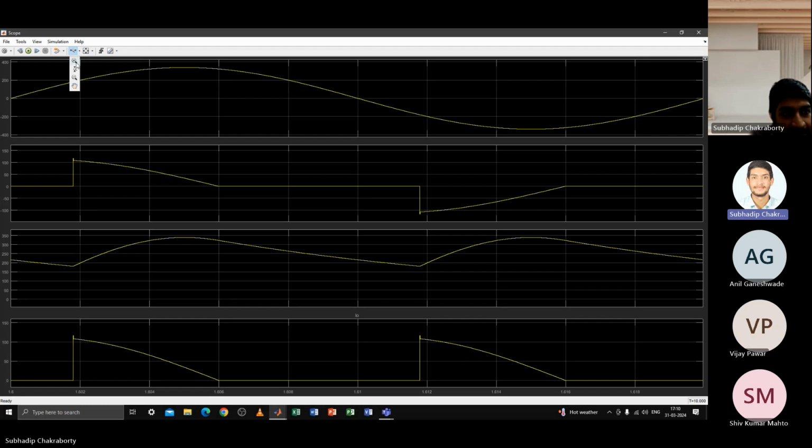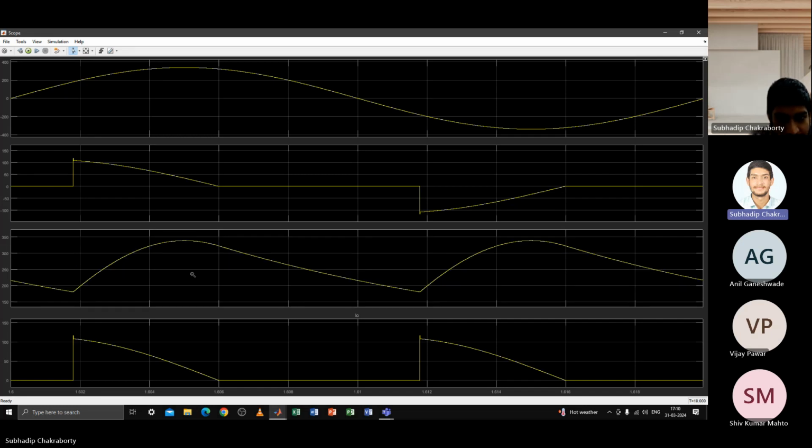Yes, so what I am saying is, just consider one sine cycle, and focus on the 0 to 180-degree period, of either the positive or negative half cycle. Then you see two instances. When will the capacitor charge? The capacitor has some initial voltage across it, so it will keep the diodes reverse biased until the supply voltage exceeds its threshold. Just assume a midway situation: the capacitor already has some charge, that is V0, the average voltage across it, and only when the supply voltage exceeds that will the diodes be forward biased.